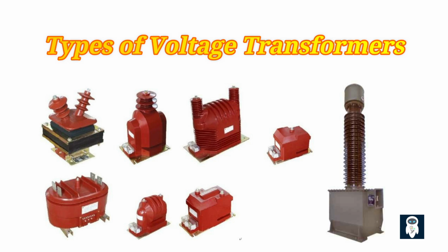2. The other type of VT is the capacitor type. This kind of voltage transformer will be equipped with a capacitive potential divider, which will be linked between the mainline phase and the ground. As a mixture of the capacitive voltage divider and a magnetic transformer, this converter can be thought of as a hybrid device of sorts.